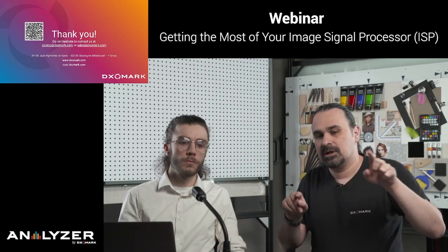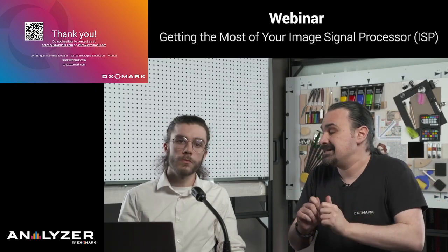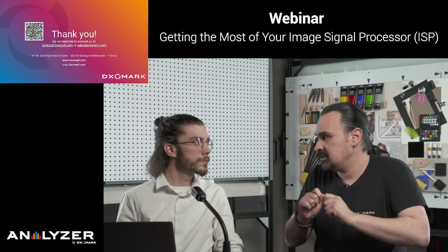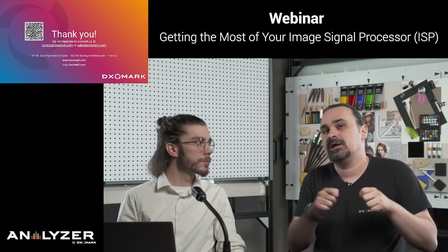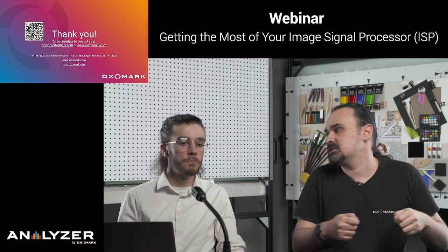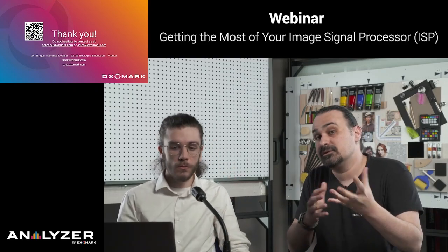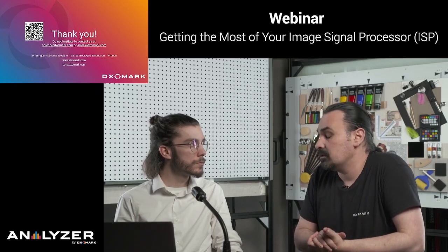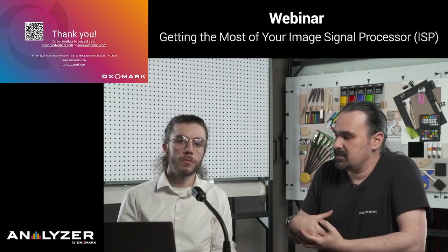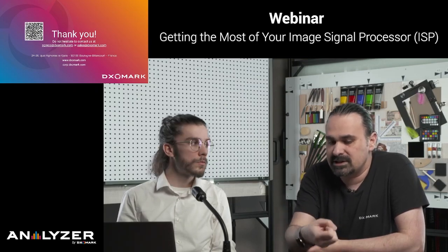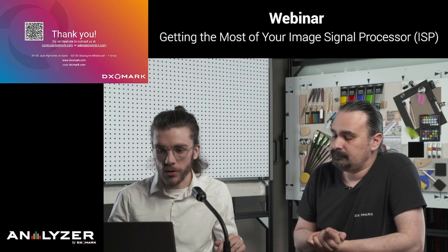And you measure how much vignetting you have and how much noise you have, and you can compute how your SNR would change if you correct it perfectly. And so you put a target on that, and you compute automatically your curve for that lighting condition, and so on and so forth. It depends on what kind of degradation you want to correct and what blocks you have available in your pipeline. But generally speaking, yes, you can integrate our measurement tool directly in your automated tuning pipeline. Yes. Okay, thank you for your question.